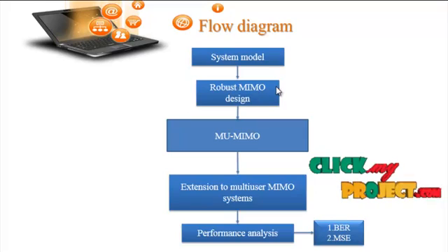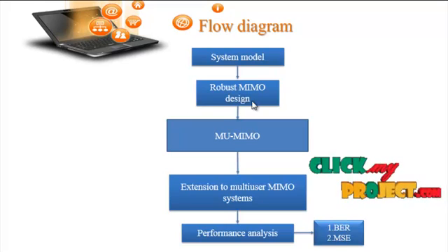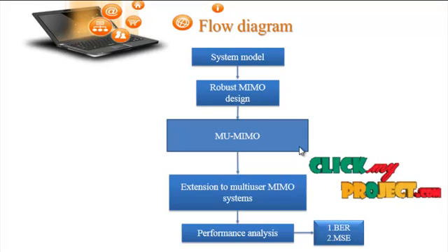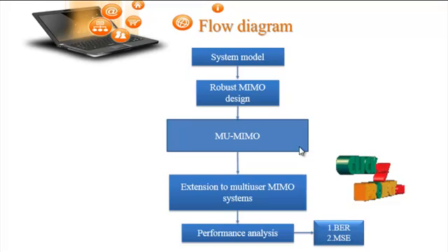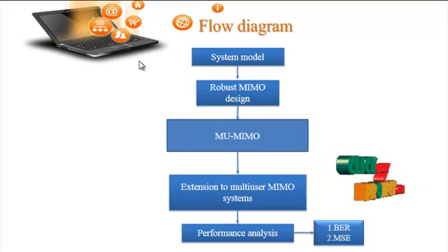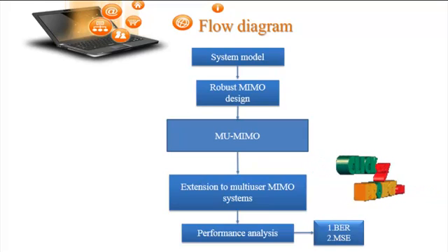In this robust MIMO relay design, we develop two iterative algorithms, namely the tri-step and bi-step algorithms, to optimize the source and relay receive matrices. Basically, this is the concept for optimizing the problem, and optimizing the scheduling is an important process in the MIMO concept. In the tri-step algorithm, the source, relay and receive matrices are optimized iteratively by solving the convex subproblems of the process. Whatever the case, using MIMO is the best process.